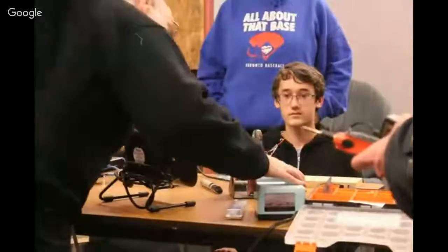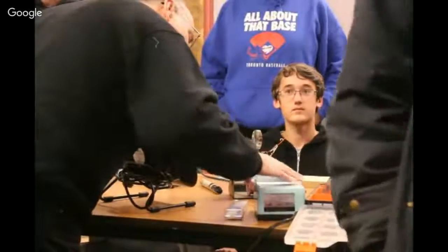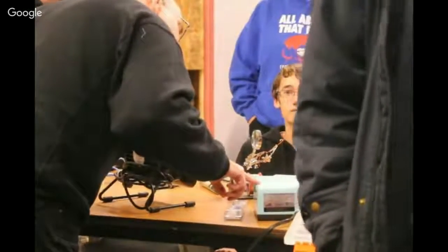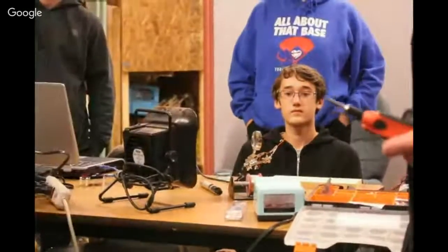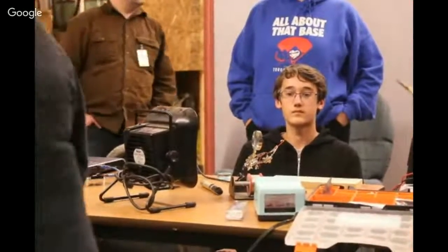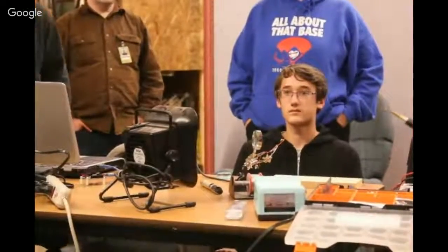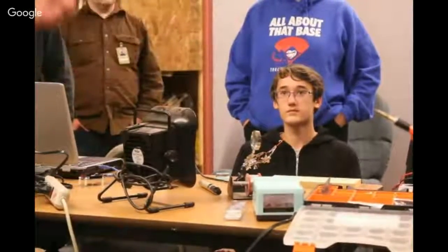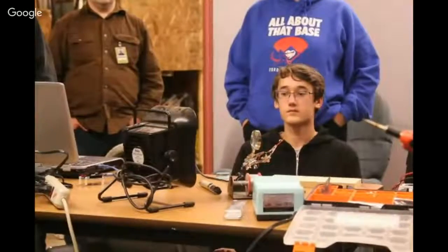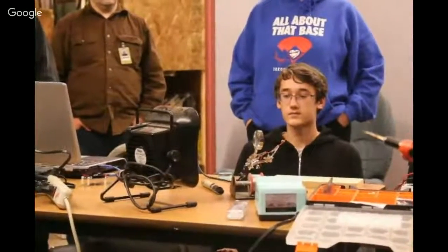My iron over here has a numerical readout. I really like soldering at about 415 degrees. That seems to be kind of the sweet spot for me between melting the solder nicely and not overheating things in a reasonable amount of time. If you have a single setting, you don't really know what that temperature is, but you learn to work with it and figure that setting out.